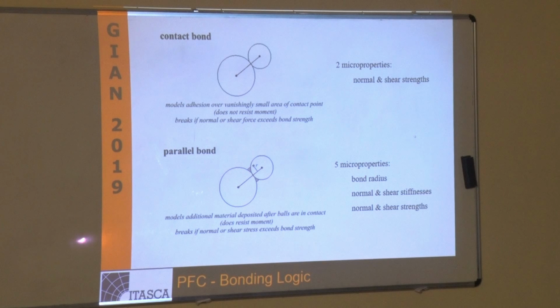And if the code with a set of properties tells me that it's a shear failure, and another set of properties tells me it actually is a tensile failure, that's a problem. How am I going to remediate or try to solve that problem? That is one of the challenges in calibrating these types of systems, where you look at micro properties and you have a lot of them.